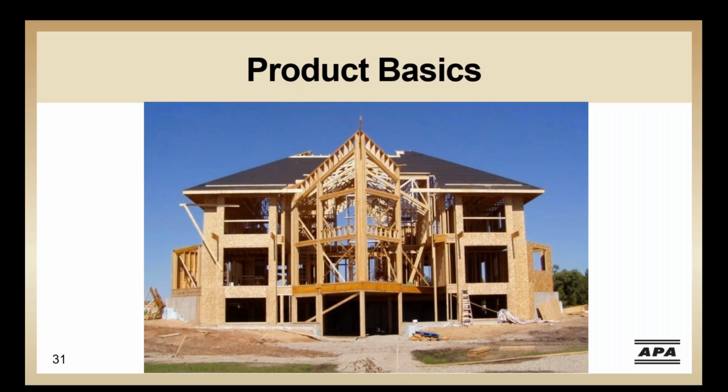With long studs and columns, there's no hinge connection in the middle of the wall, so there's no loss of strength. Glulam and SCL attributes are perfect for resisting wind pressures and associated deflection perpendicular to the wall. Both glulam and structural composite lumber are available in 2x4 and 2x6 standard wall framing depths.